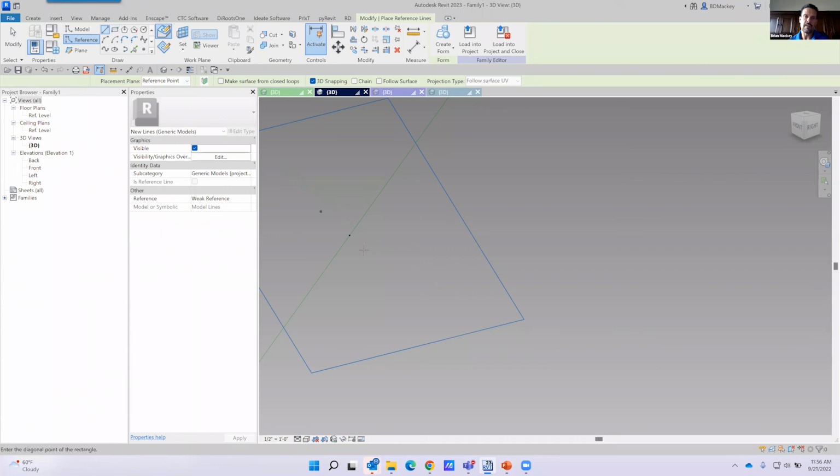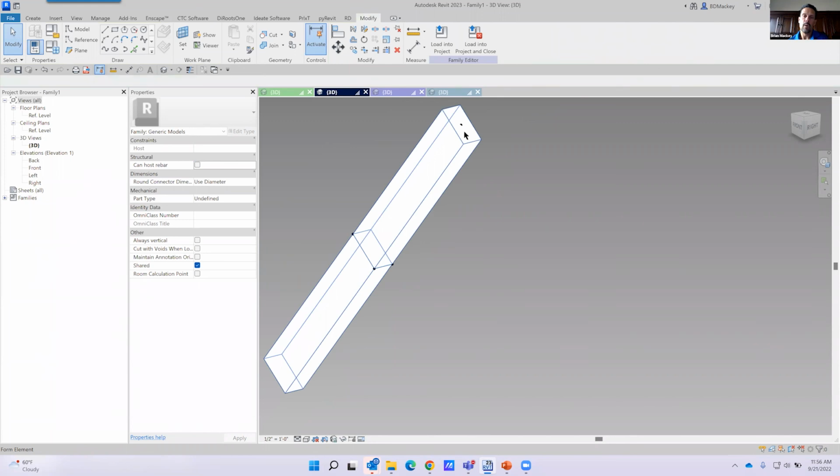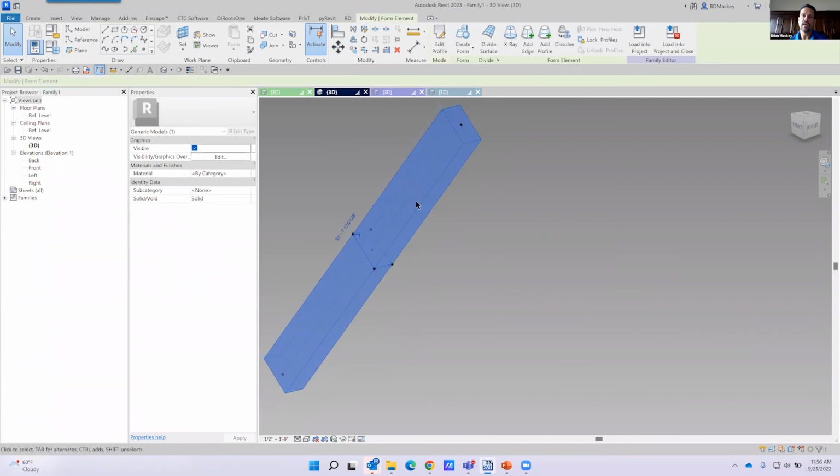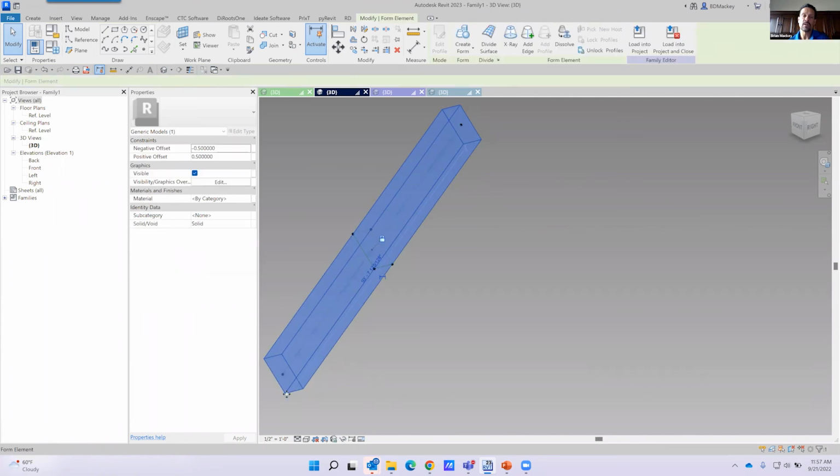Rectangle. One of the things that I found when I was trying to do something like this that became really, really weird is when I created a form, I wanted to change the size of the ends. There's this button up here called lock profiles. If that is highlighted, then it's going to be locked, and what it'll mean is you're getting consistent thickness going down. This is particular when you do sweeps.